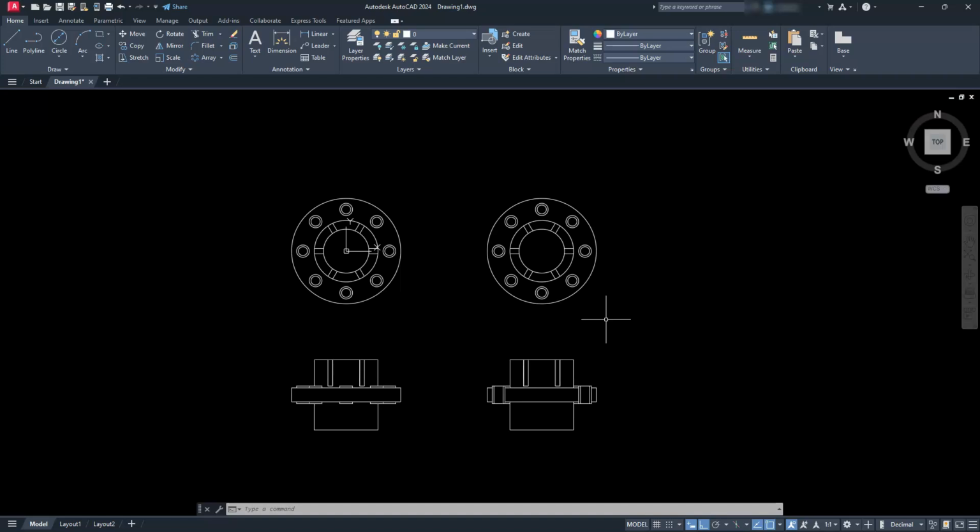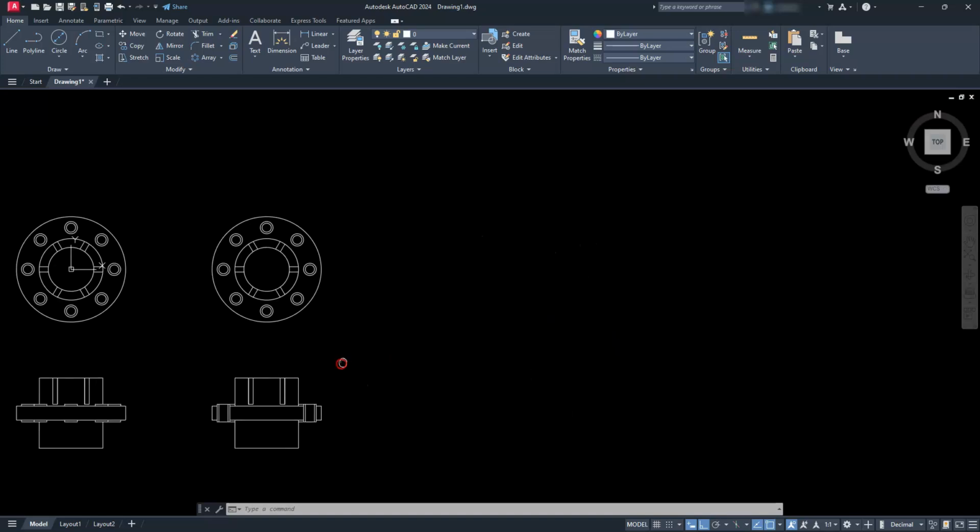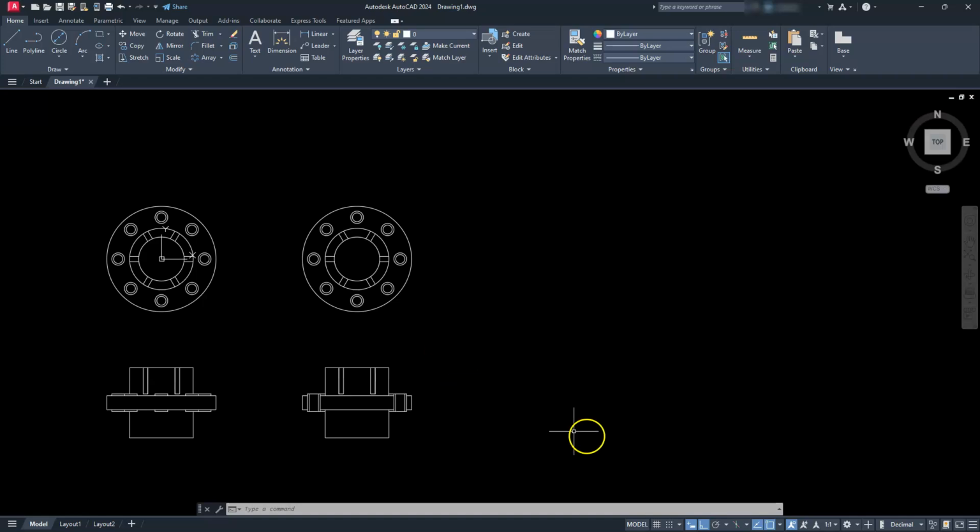All right. So the next step we're going to do is going to be the isometric. So the first thing I like to do in isometrics is switch over to an isometric view by selecting here. So now once I'm in the ISO draft mode, I'm going to switch to isometric top, and you can use the F5 button to toggle, right? So I toggle to ISO top. I'm going to type in EL, enter.